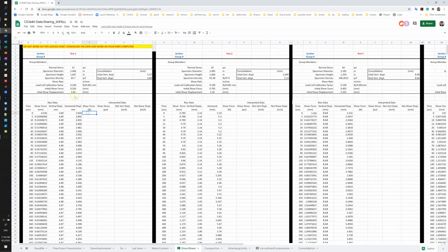So to do that, we need to make use of the calibration factors. The first thing you would do is offset the dial gauge, because when we start recording the data, you don't want it to start at 0. It's very hard to adjust the pointer to be exactly at the 0 position. You also want the spring, which is the dial gauge, to work at its full capacity, where the midpoint of the spring is the most accurate position.